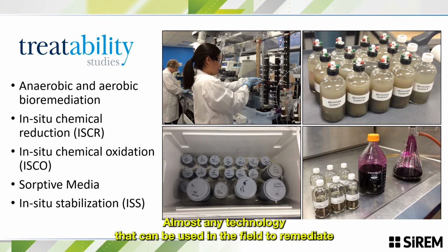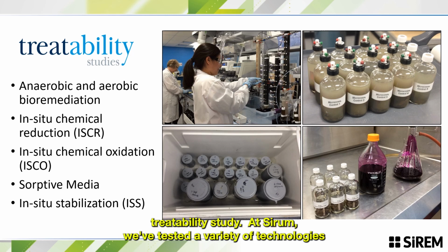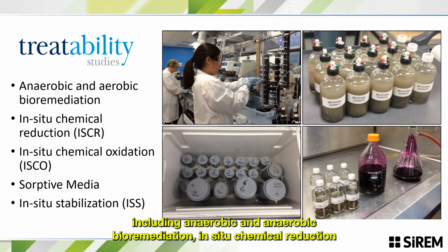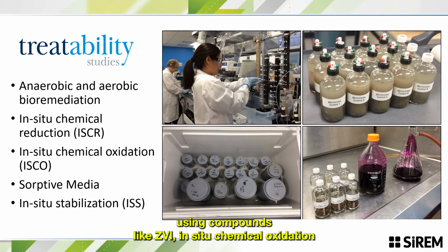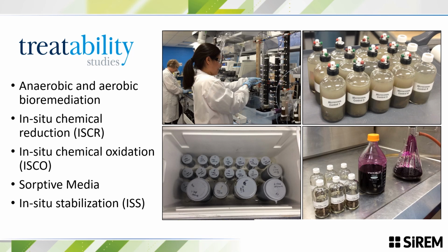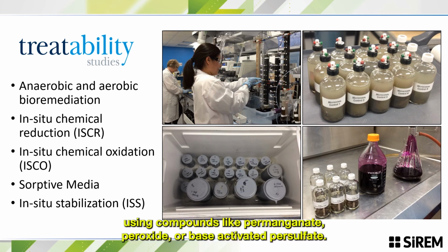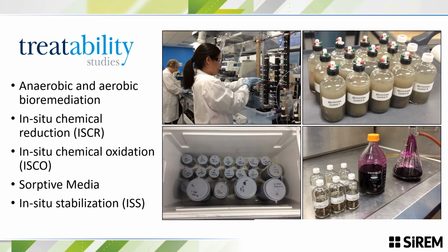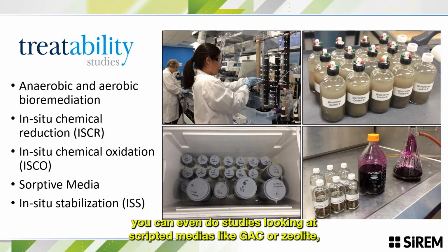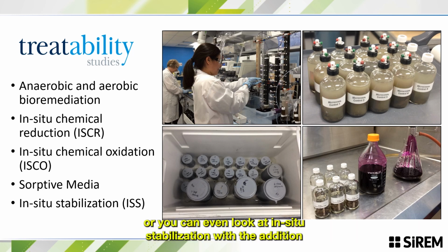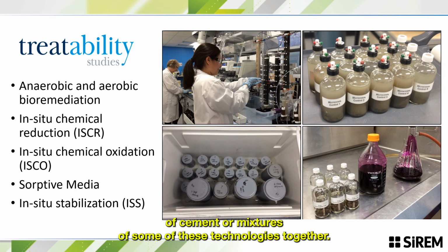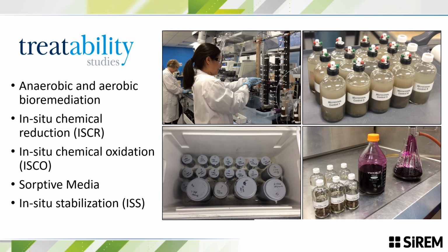Almost any technology that can be used in the field to remediate a site can be tested using a bench-scale treatability study. At SiREM, we've tested a variety of technologies, including anaerobic and aerobic bioremediation, in situ chemical reduction using compounds like ZVI, in situ chemical oxidation using compounds like permanganate, peroxide, or base-activated persulfate. You can even do studies looking at sorptive medias like GAC or zeolite, or you can even look at in situ stabilization with the addition of cement or mixtures of some of these technologies together.